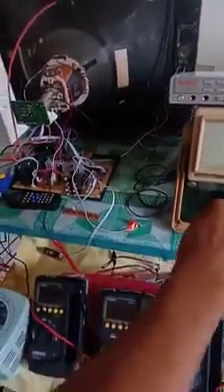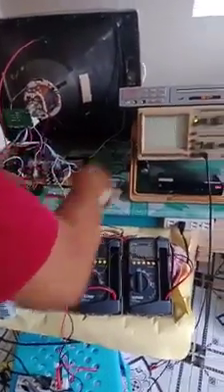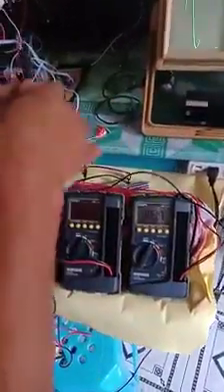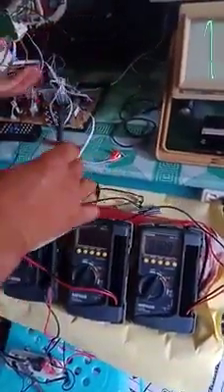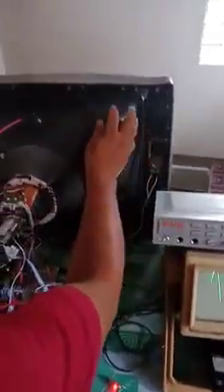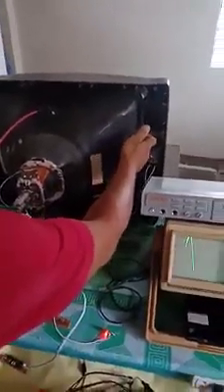Okay, we have here. By the way, how do we measure the voltages of the circuit? We will set it to DC voltmeter. The negative side should be connected to the negative side of the circuit. Where is the negative side of the circuit? It could be this bare harness wire that hugs the outer conductive coating, which is the negative side of the picture tube. The negative side of the picture tube is connected here to the negative side of the CRT drive, and finally connected to the main board, which is negative.